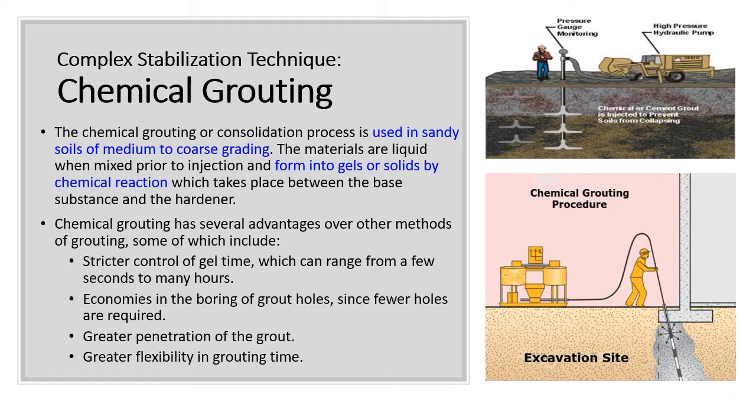For fine-grained sand, chemical grouts of low viscosity can be used, and for the very finest sand, expensive resins of very low viscosity may be used, but spacing between holes must be low and injection rates also should be slow. Chemical grouts reduce permeability by void filling and strengthen the ground formation.